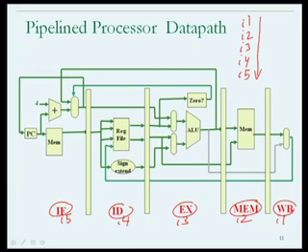So this is the order in which your program is executing the instructions. And if I looked at the hardware within the processor, I might find instruction I1, in other words the first of them, occupying the write back hardware, at the same time that instruction I5, the last of them, is occupying the instruction fetch hardware. Now to make this work, it may be necessary to remember some of the information that is being passed between the IF stage and the ID stage.